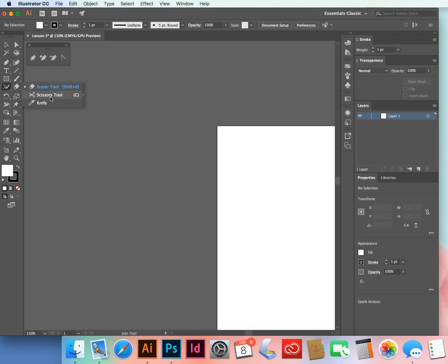We use the scissors tool, which is C on the keypad. So all the tools have a shortcut and it will show you what the shortcut is on the right hand side here. So scissors tool, rotate tool, tend to use the reflect tool more than the rotate tool, but again we would probably use the keypad, but you can click on that. All these other tools, we do use them, but just for the beginning of trade sketching, we'll probably ignore all those until we need them.